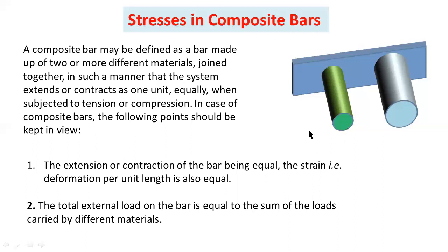Here you have to remember that the total deformation, or total strain, or total elongation or contraction in each bar is the same. And also the total load carried by the compound bar is equal to the sum of the loads carried by each bar.